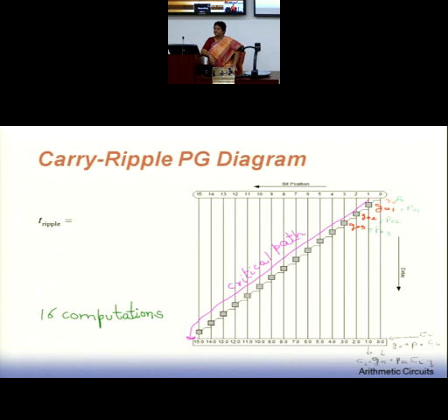So Radix helps in reducing the depth of the tree. But then when you increase the Radix, what's the penalty you are paying? Can you anticipate? Now your circuits are becoming complex, because your G02 would have been only G0 ANDed with G1. Simple. A 2-input AND gate would have sufficed. Now when you go for 3 blocks to be combined together, you require a 3-input AND gate. Or you require a 4-input AND gate to get a G04 together in the single step itself.